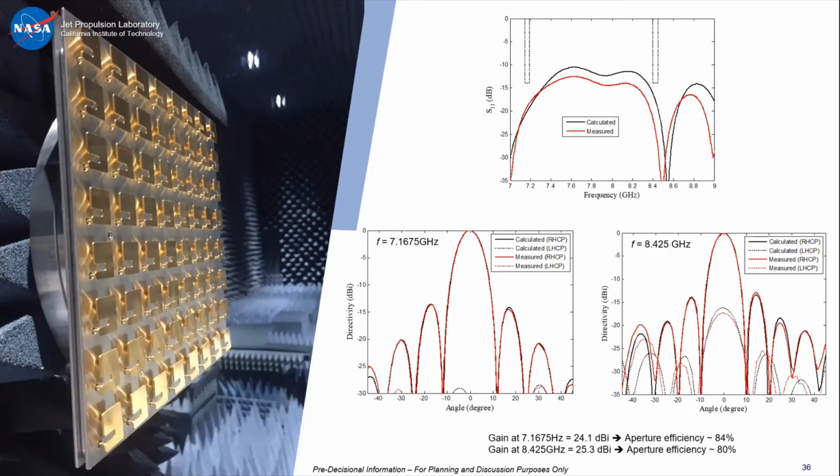Most of the time they use horn antennas. Multi-flare horns are very convenient at terahertz frequencies because you can just drill and make arrays of them. And then there are other designs that are entirely micromachined antennas as well. So they do horns, they do metasurface antennas as well, like the one that I was just showing, entirely made of metal. David Gonzalez designed one he called the fakir bed antenna. It's made of posts, where the height of the ground below the post changes. There are a lot of antenna solutions at terahertz, but you need to be cognizant of the losses that you will incur with the different technologies that we use. And that's why horn antennas are usually the best way to go for terahertz antennas.